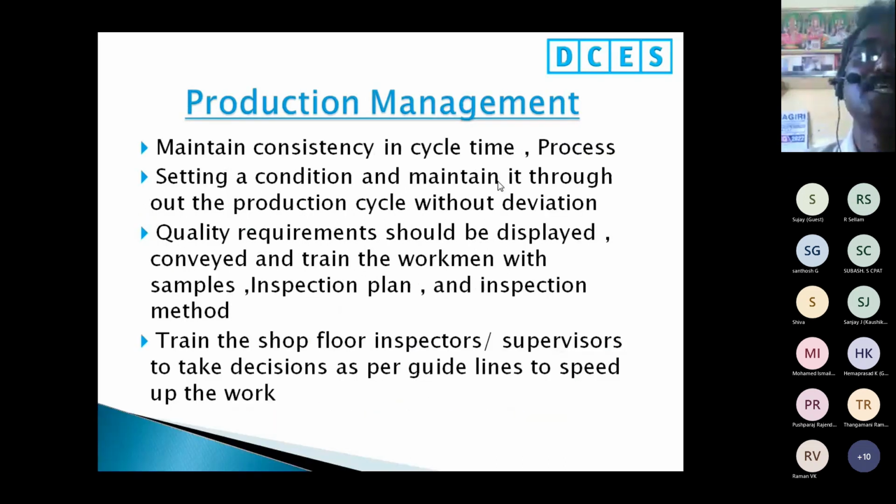Maintain consistency in the cycle time and the process. Set a condition and maintain it throughout the production cycle without deviation. So here, setting a condition means when you load the die, the condition should be followed for each and every loading. It will give you a good output and quality.